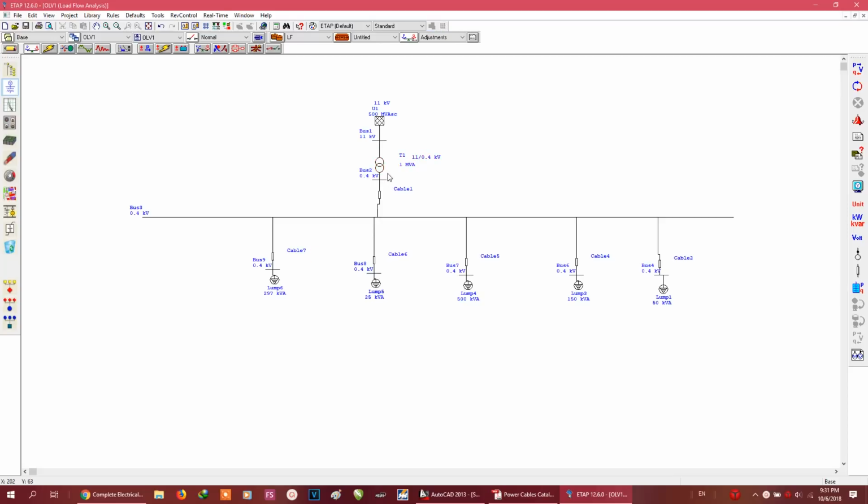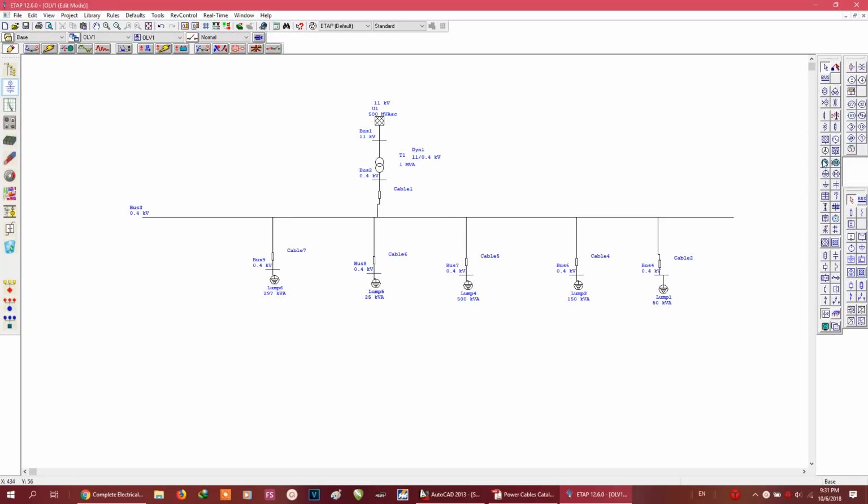You know that this transformer supplies a current, and this current carries the P and the Q, the active and reactive power. If we add here a capacitor to supply the reactive power, then the current absorbed by the transformer decreases, therefore the voltage drop on the transformer will decrease. What I mean, let's get back to the editing. Add a capacitor, like this.